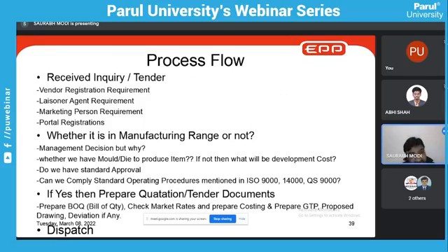But on the other side, it has a problem as well: FRP can never take up higher pressure. In fluid mechanics we have studied pressure is equal to rho g h, right? So it applies in a storage tank, where FRP can resist that static head. But if you want to store liquid or any fluid at higher pressure, then FRP is not a good choice. In that case, you will have to go towards metal only. Okay, so this was from my side. Thank you everyone for listening to me.